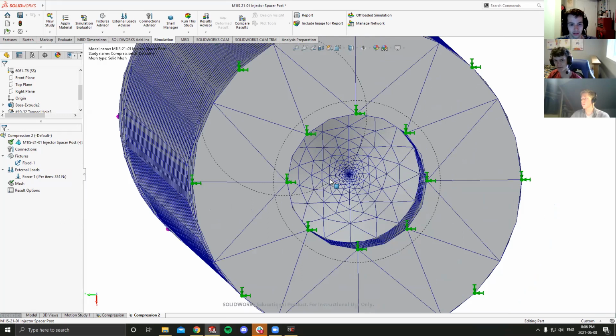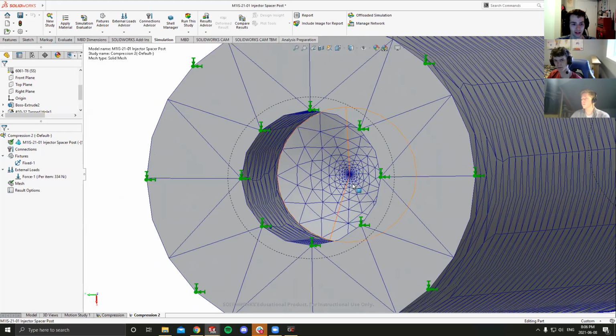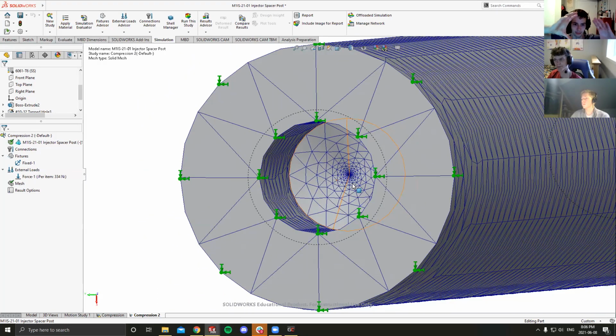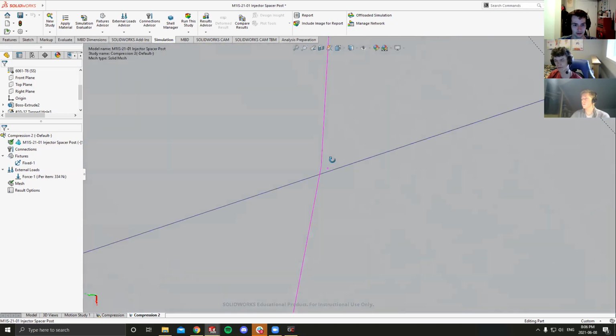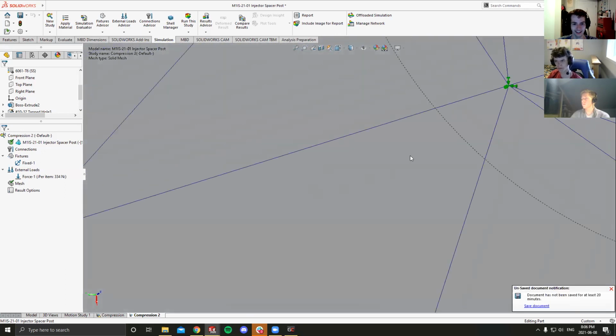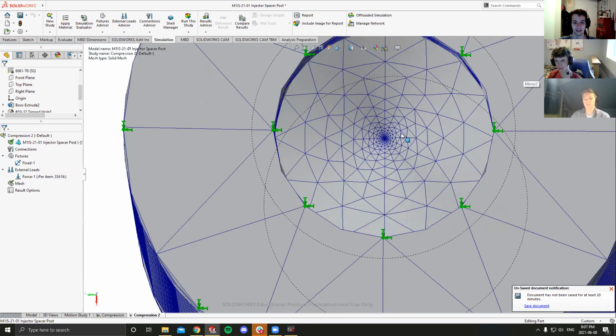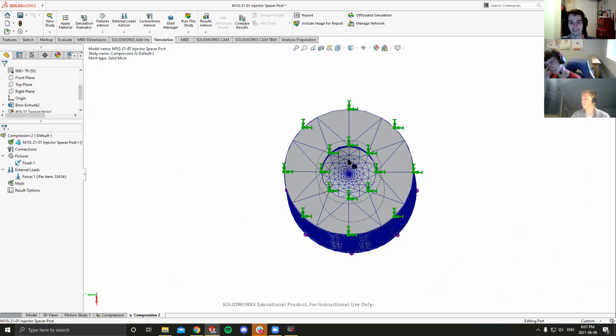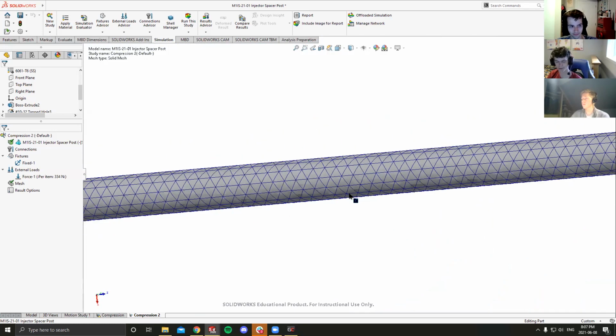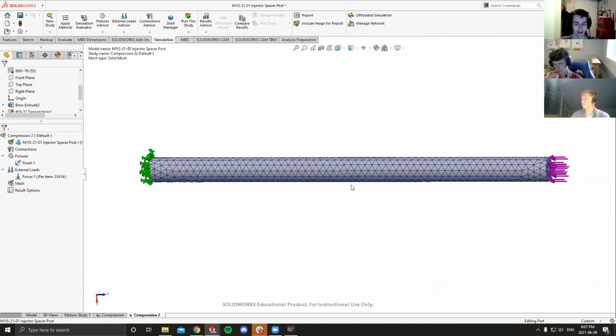That's really good, because the smaller our geometry is, the more likely it's going to be messed up by an oversized element. If we have an element that's way bigger than the relative geometry around it, that's how we get those errors. You can see it's scaled nicely to this definite point at the end of our hole. This being said, our analysis is very much not on the inside of these holes, but this is still important to know.